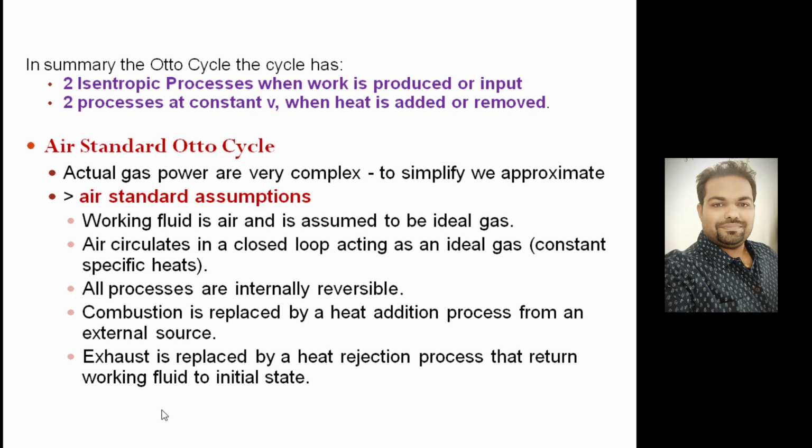That means in the actual case, what is happening is we are taking the air inside and mixing the fuel into it in a certain proportion, then we are burning it. The moment we are burning it, air will not be air, it will become gas, carbon dioxide. So if we are not releasing that gas and we are again cooling it, when you are cooling it, it will form carbon deposit. And you will not have the same mass of air inside.